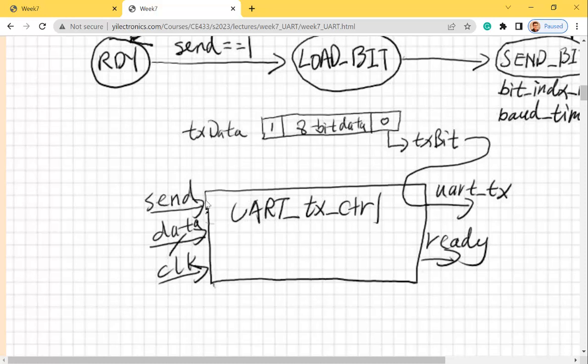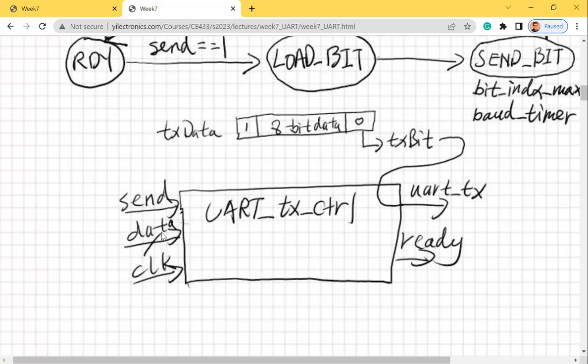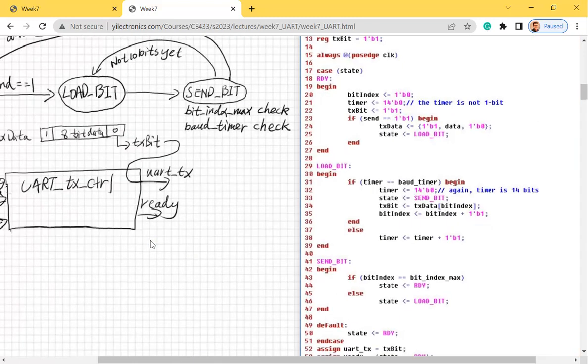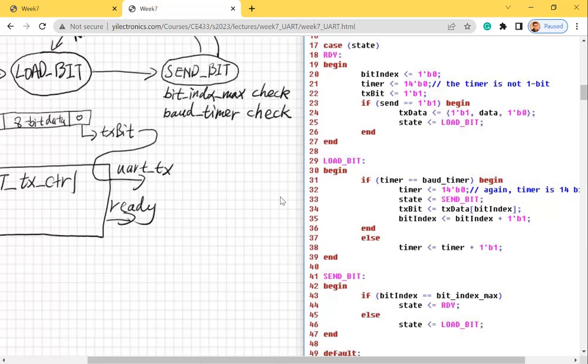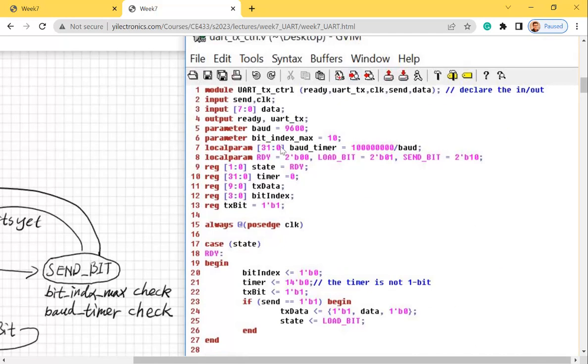So the TX module won't be able to tell anything about the data. It can be nothing, all zeros, all ones, whatever. It can be an error code. It's going to send it. Just keep in mind, whenever the TX module is sending something out, it assumes that the data here is ready to be sent. First, remember there's a baud rate, which is like the 9600 I've been using for the microcontrollers. So you need to specify that in your Verilog.